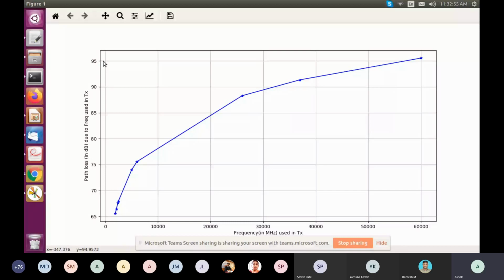On the other hand, the advantage of going for a higher frequency like 60 gigahertz is that you have large amounts of unused bandwidth there. So if you're able to come up with an RF system and antenna based design where you can reliably communicate there, of course at very, very short distances, then you have a large amount of bandwidth available there. And that is what is typically referred to as millimeter wave communication, which is happening at 60 gigahertz, 28 gigahertz, at different standards, right?